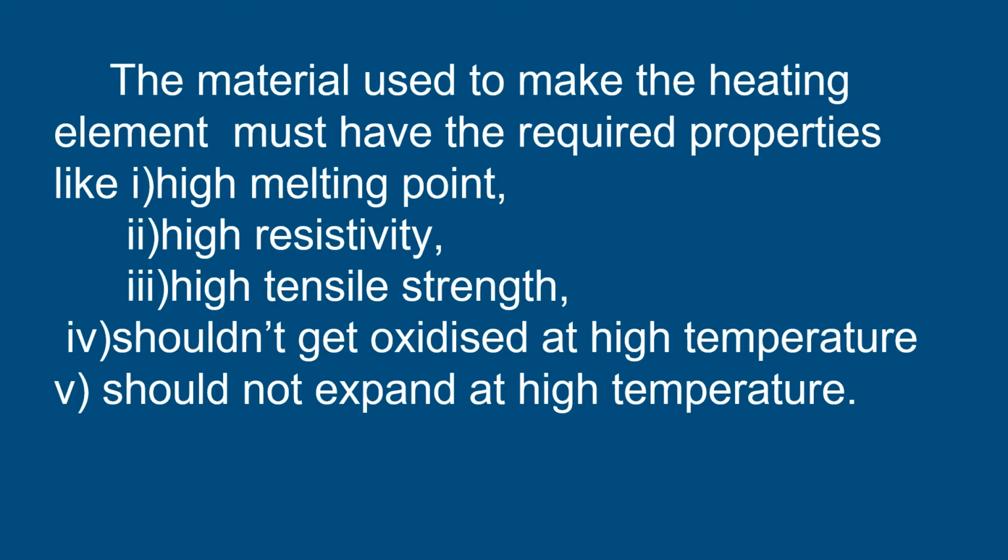So this heating element is the main core part of the electrical appliances, and it should have certain properties to achieve a high heating effect in them. Let's see what those properties are. The first one is high melting point. Next, high resistivity, high tensile strength, it shouldn't get oxidized at high temperature, and it shouldn't expand at high temperature. Let's go back to the first point, that is high melting point.